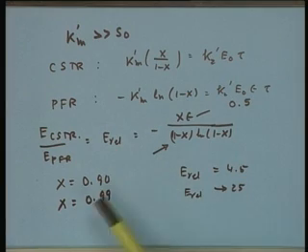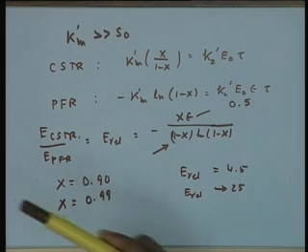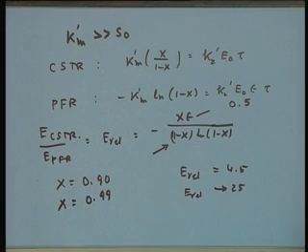That gives us a significant advantage for using immobilized enzymes in PFR, and that is one of the reasons why you will notice in the literature that almost 70 to 80% of the total reports on use of immobilized enzyme are in a plug flow reactor. The advantage lies in the quantity of enzyme required, and of course this advantage will keep on reducing, that means the relative quantity will keep on reducing if we shift from first order to zero order. Ultimately it will reach the same quantity.